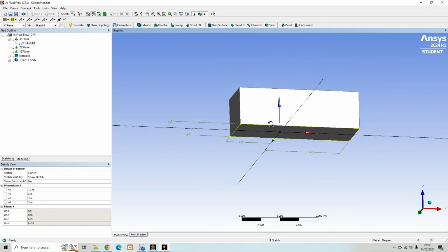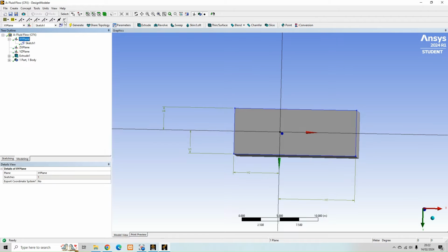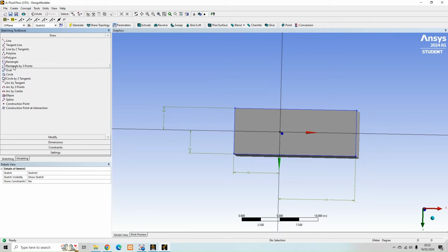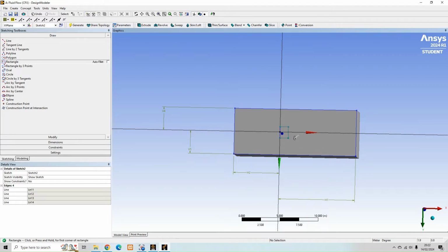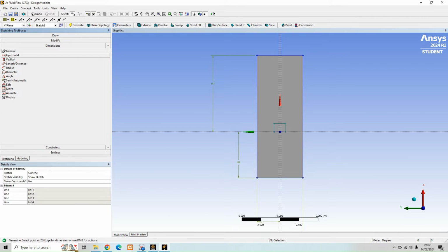So next we want to sketch our cube, and we're going to sketch on the bottom face here. So we'll create a new sketch on the YZ plane. And this time just make sure it's coincident with that y-axis, because that will just hold the front face there. Don't have to be perfect sketching it out, because we can always correct it in a minute, like so. So add your dimensions.